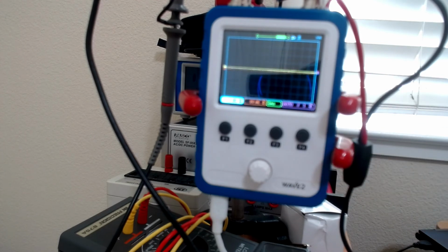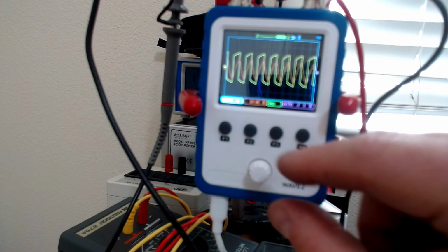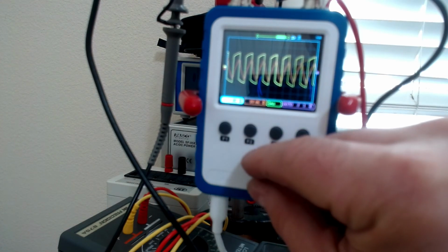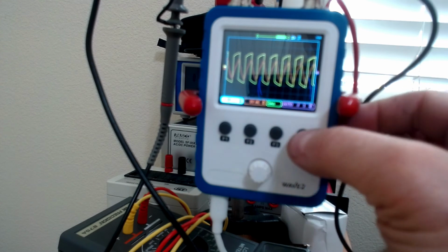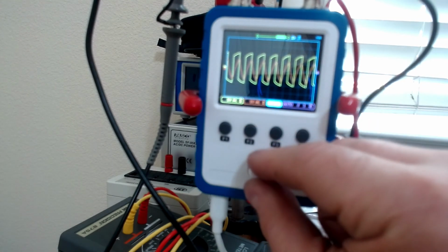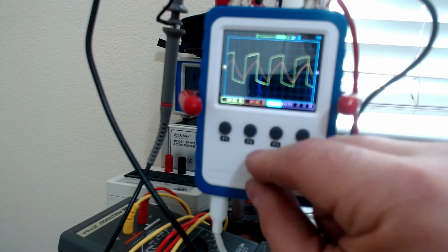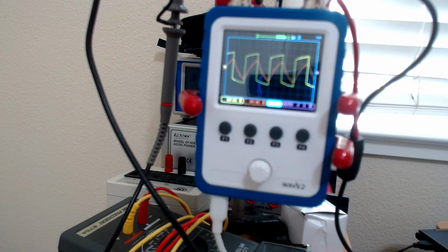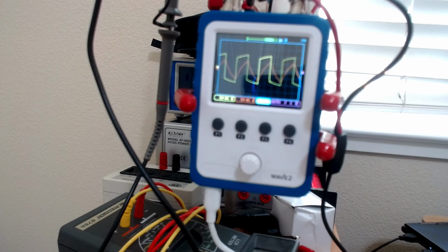So let me increase the frequency again, to give you an idea of what happens if the signal changes very rapidly. Oops. You see the capacitor doesn't have enough time to charge up because I'm switching between on and off too fast. Okay, this is a little bit blurry. So you'll be doing this experiment later on this semester when you learn how to use the scope.